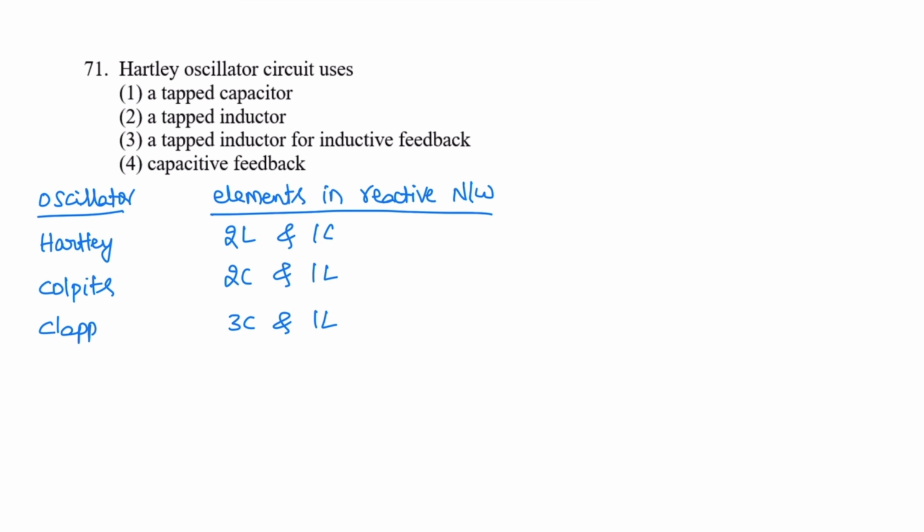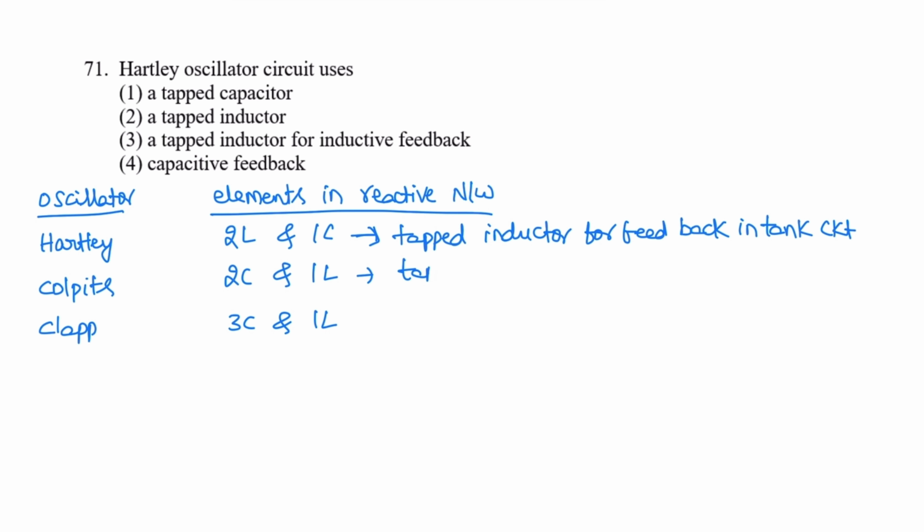The Hartley oscillator uses a tapped inductor for feedback in the tank circuit, and the Colpitts oscillator uses a tapped capacitor for feedback in the tank circuit.